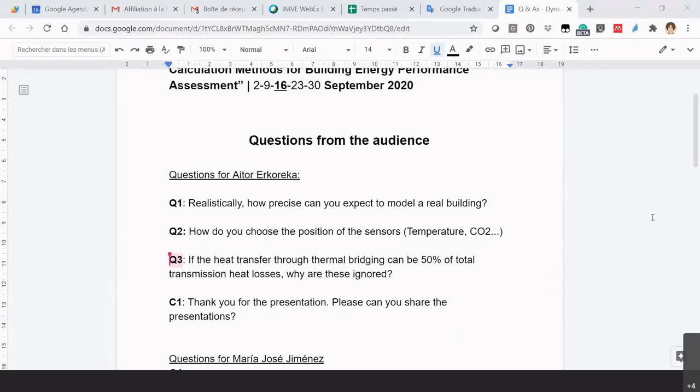So you have to put it on an interior wall of the building, and it must avoid air currents and, very important, direct solar radiation. And you cannot put it next to heating devices or devices that are producing a lot of heat. And the height of the sensor must be about 1.5 meters in normal rooms.